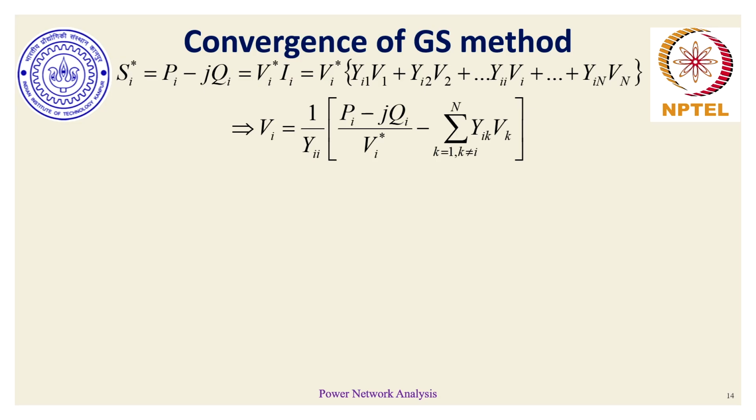So to do that, I'll take a very basic approach. Basically in Gauss-Seidel, what I'm trying to do is equate this term with respect to this term, and I'm assuming that everything on the LHS, which is the first ticked box, is known. And on the right hand side, I'm trying to find these voltages which, if found, should equate these two boxes. And the same equation in Gauss-Seidel form gets rewritten in this fashion.